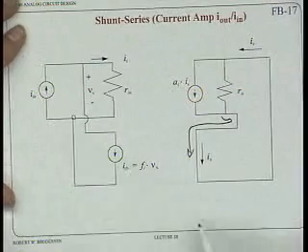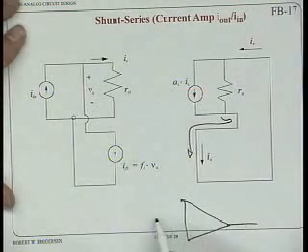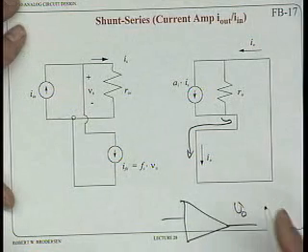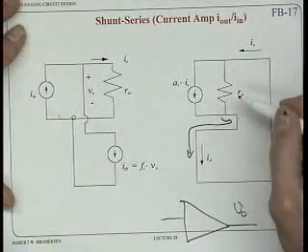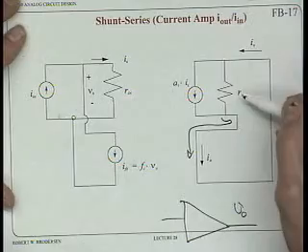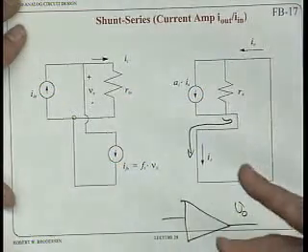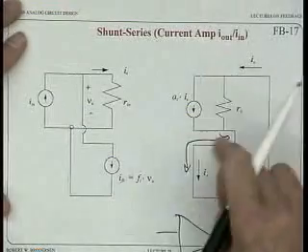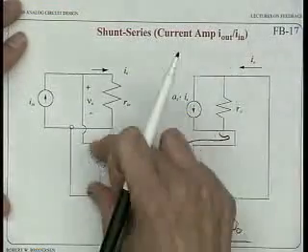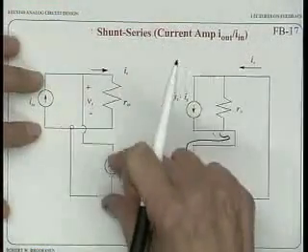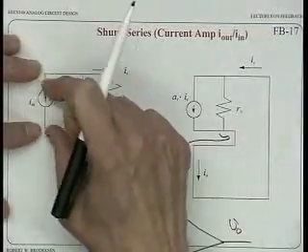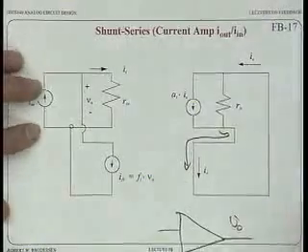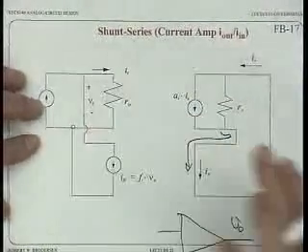This is very different from when you generally think about op amps. You can't really do series sensing. You only get a voltage out of a typical op amp. So when we do series sensing, we're actually having to work with our transistors, and I'll show you how to do that in a second. Basically, the sensing is in series. Now we're feeding back in shunt, just like before, so it's in parallel with the input. So I error is equal to I feedback minus I in. So here's a shunt series.